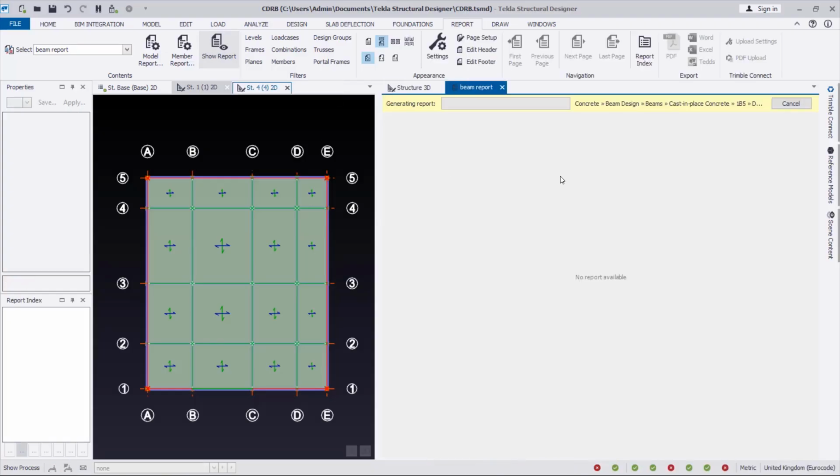Click here, and this is going to combine the report you actually arrange in the model report and the one in the member report together to give you a complete report of that particular member in terms of the calculations, in terms of the bending moment, shear force diagram, and as well as the necessary informations you need to actually check the beam for a good design successfully.